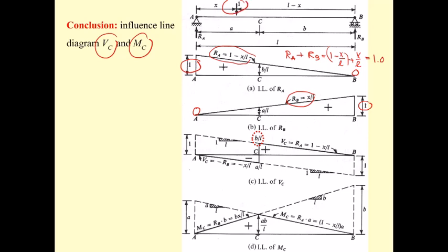And then when we come to the shear diagram, the shear diagram starts at 0 from here, and goes downward to minus A over L here. And since the force here is 1, it jumps up to B over L. So the combination of this is going to be 1.0, and also they are parallel, and the end at B is going to have 0 value.